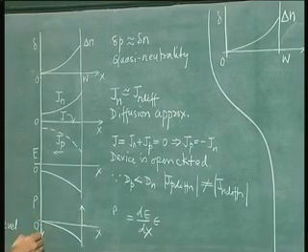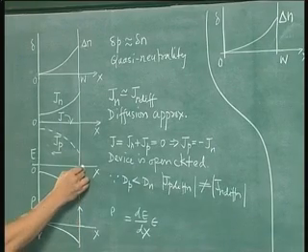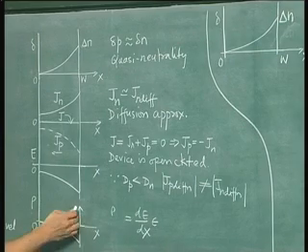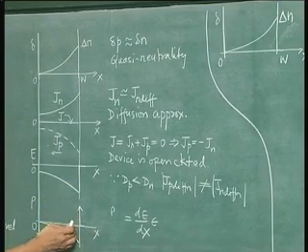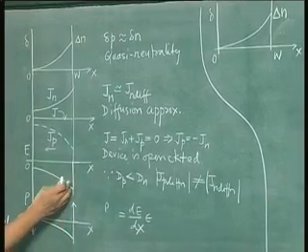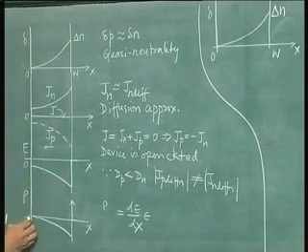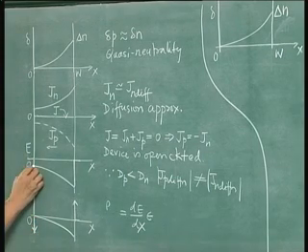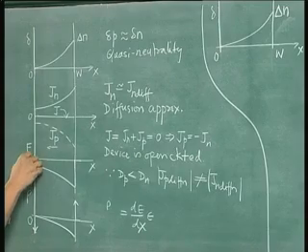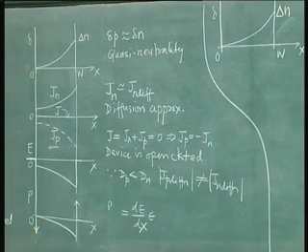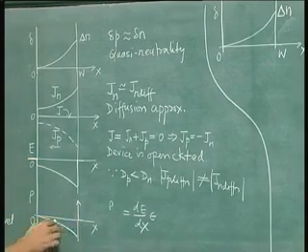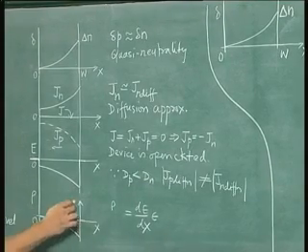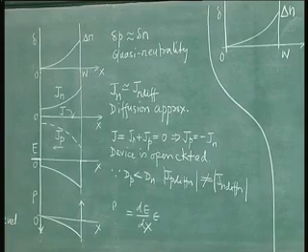Now there are two impulses here. This impulse is because there is a step in the electric field like this. So this is the positive charge sheet from where field lines emanate and they terminate throughout the bulk, and that is why the field decreases, but some lines still remain when you come to this end and they terminate on a negative charge sheet that is shown here. So from Gauss's law, it is this step that is responsible for this particular impulse. So the area under this curve plus this will totally show the negative charge, and this shows a positive charge. These two charges will be equal.